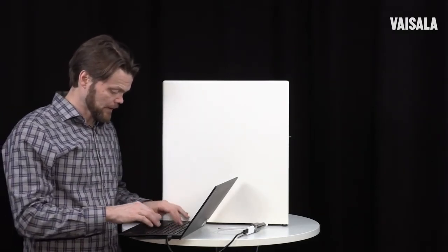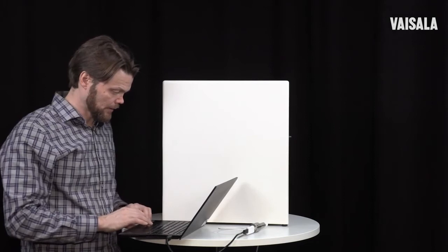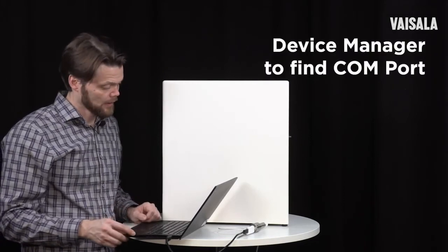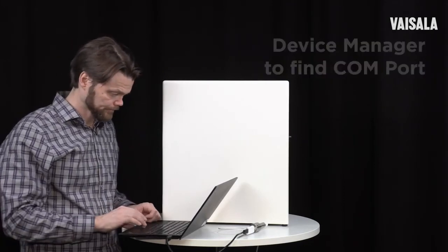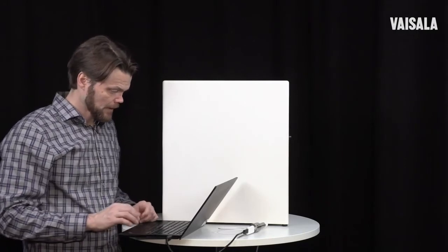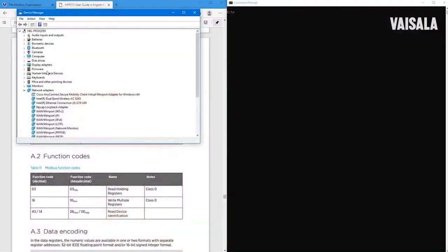In order to find that, we have to open Device Manager in Windows. You should look for these ports, COM and LPT, and here you should find Häusler USB device, and in my configuration I have this in COM 11. You probably have a different COM port there, but keep this in mind.